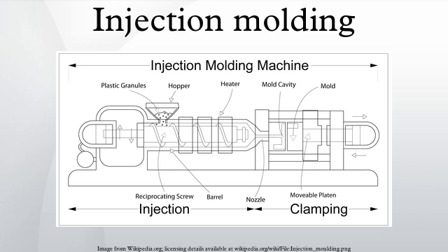A parting line, sprue, gate marks, and ejector pin marks are usually present on the final part. None of these features are typically desired, but are unavoidable due to the nature of the process. Gate marks occur at the gate which joins the melt delivery channels to the part-forming cavity. Parting line and ejector pin marks result from minute misalignments, where gaseous vents, clearances for adjacent parts in relative motion, and/or dimensional differences of the mating surfaces contacting the injected polymer.